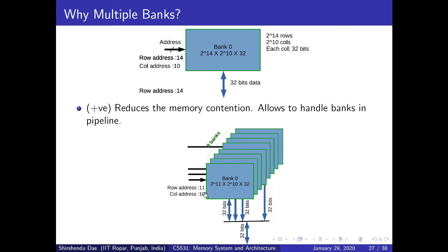Sense amplifier is internal to each bank. This bank has its own sense amplifier, this bank has its own sense amplifier. After the sense amplifier, when they are sending the information to the outside world or through the DRAM controller, they are using a shared bus.